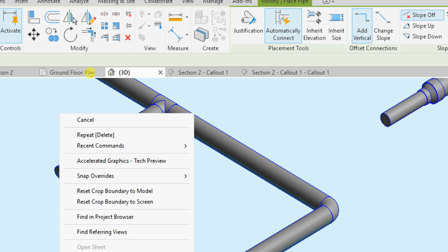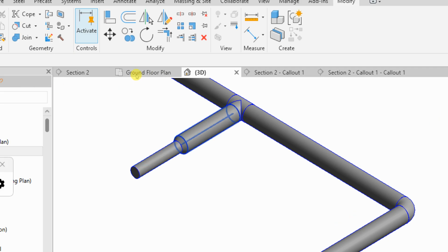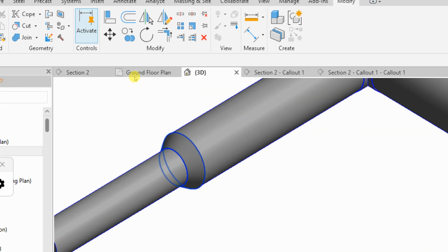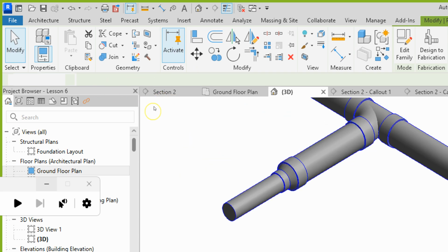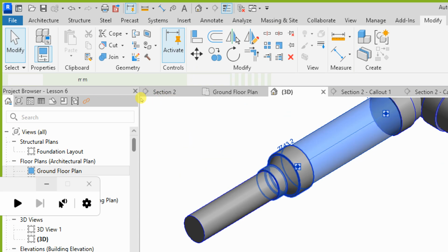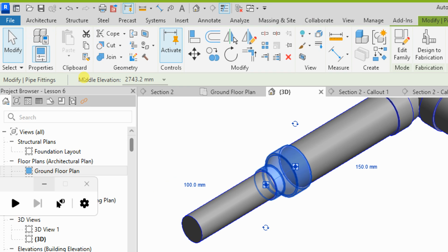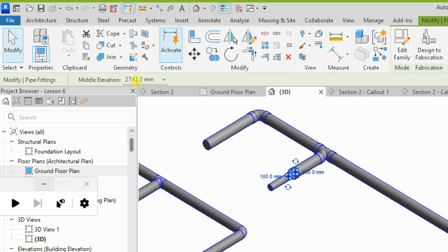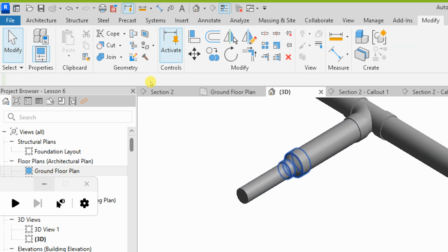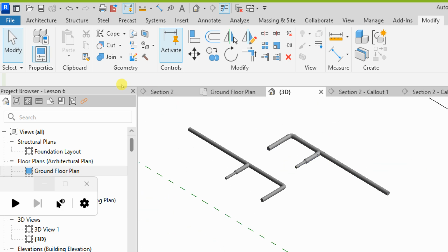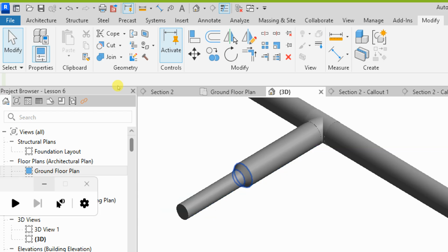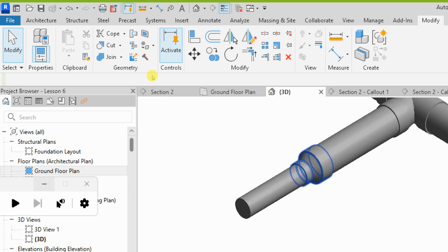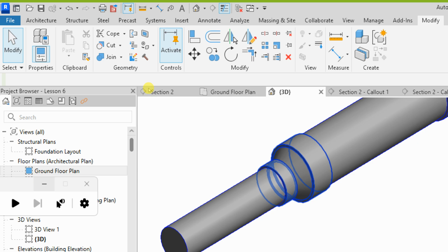Now, if you look at the transition for the two of them, this one is giving me a different transition here, standard pipe. See the transition type is this type, just a simple one. If I come to this here, the transition here is a proper PVC pipe. So now, when I'm producing plumbing drawings, and I know I'm going to use a PVC pipe for my work, I cannot go and show the artisan to use this kind of drawing. I need to be able to properly depict the drawing as such.